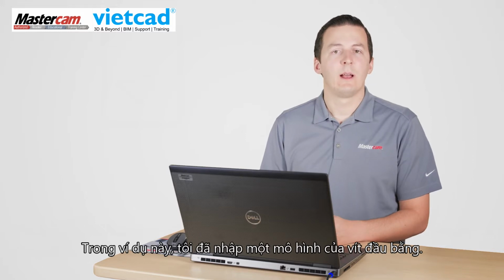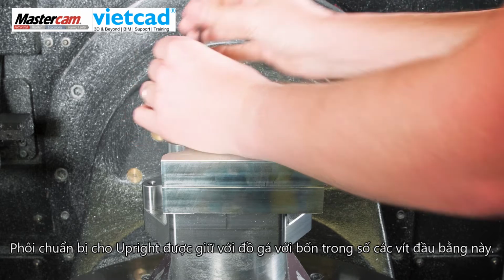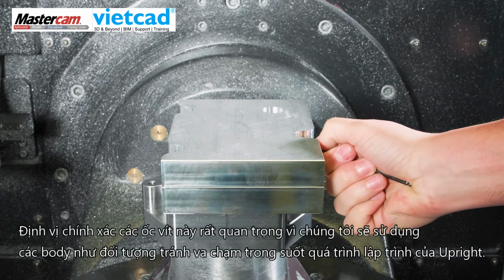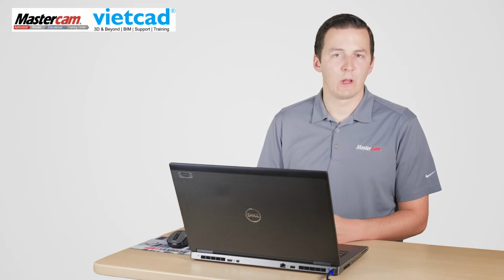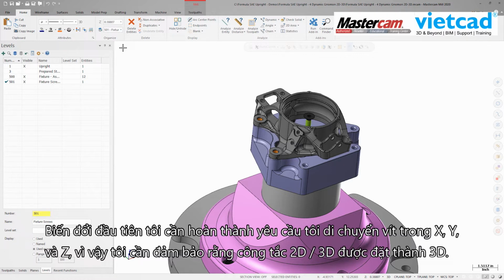In this example, I have imported a model of a flathead cap screw. The prepared stock for the Formula SAE upright is held to the fixture with 4 of these flathead cap screws. Accurately locating these screws is important because we will be using the bodies as avoidance geometry throughout the programming of the upright. The first transform I need to complete requires me to move the screw in X, Y, and Z,